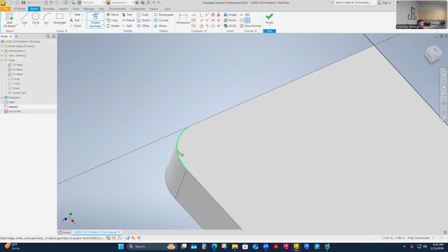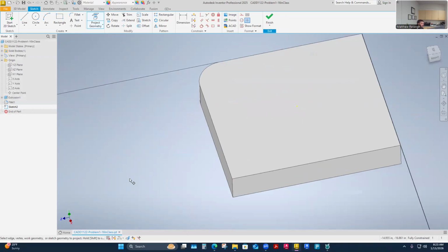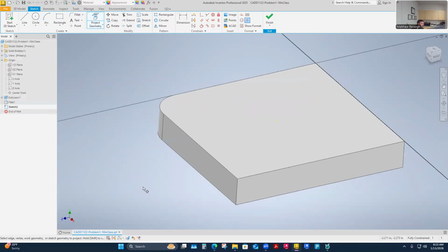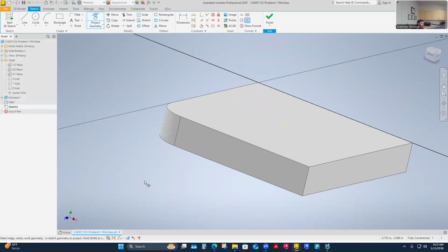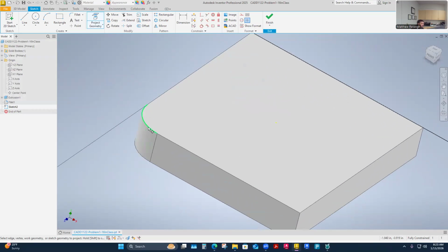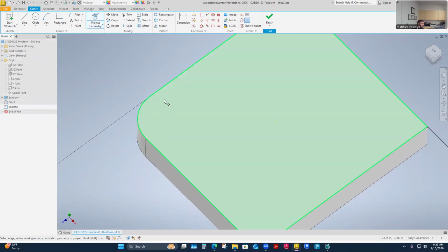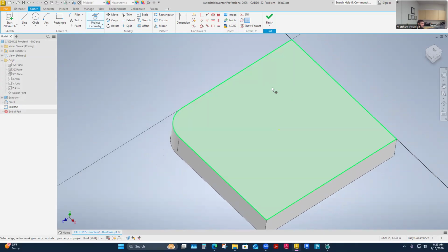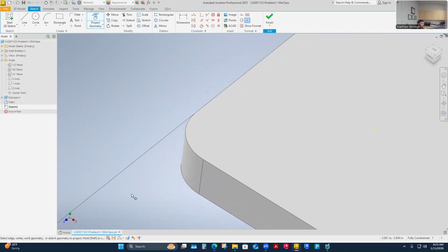This is what I mean when I'm projecting geometry, I generally turn my object in its 3D view so I can be pretty particular in which edge I select to project, just because, like I said, it'll look through this object and pick up these other edges that aren't necessarily on my surface, which is handy because I can project something that's on a different surface to my surface if that's helpful.